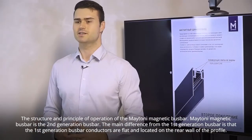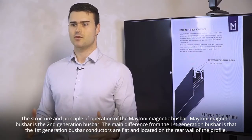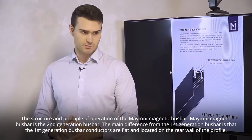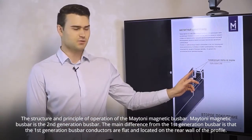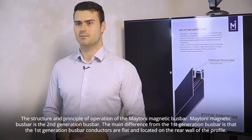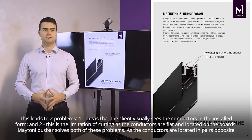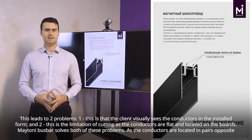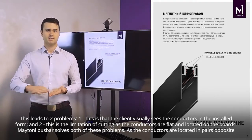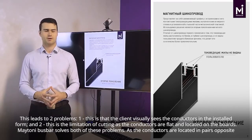The structure and principle of operation of the Maytoni magnetic busbar. Maytoni magnetic busbar is the second-generation busbar. The main difference from the first-generation busbar is that the first-generation busbar conductors are flat and located on the rear wall of the profile. This leads to two problems. One, the client visually sees the conductors in the installed form, and two, the limitation of cutting as the conductors are flat and located on the boards. Maytoni busbar solves both of these problems.